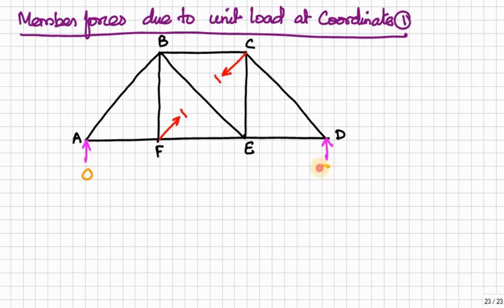Okay. So next, based upon the zero member concept, we can put 0 before starting the method of joints. So here 0, here 0, because not just meeting at inclined things. Here also 0, 0. So the remaining forces can be calculated using the method of joints.